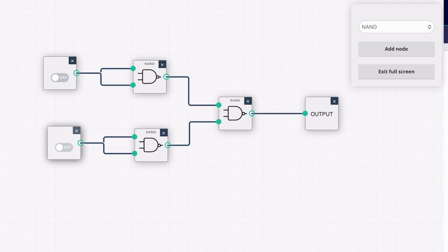So now you can see if both inputs on the left side are off, the output on the right is off. Turning one on turns on the output, turning the other one on also, and having both on also keeps the output on. So it also replicates our OR gate. And now, as this NAND gate is able to perform the actions of the NOT gate, the AND gate, and the OR gate, we can deduce that the NAND gate by itself is as powerful, or can do as many things, as the AND, OR, and NOT gate can.